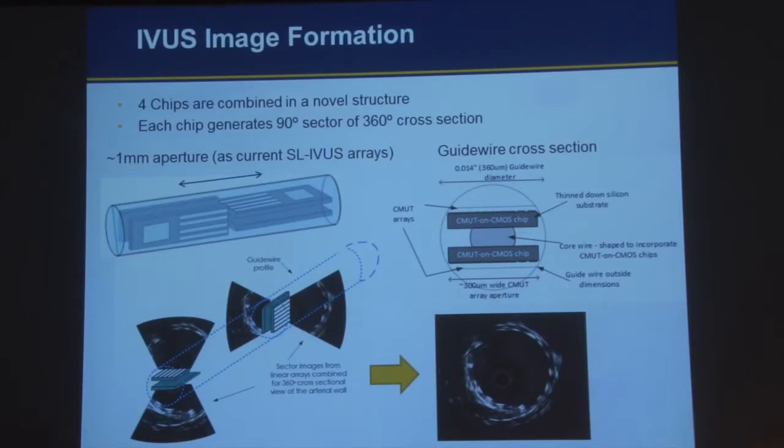And the thing is, how you put it together is exactly the same way the pressure sensor is put together. They have a chip, which we just have basically 2 chips, and they're all thinned down to 50 microns and glued and all that, so it's all taken care of. They can actually put 5 cables already, combining pressure sensor and a flow sensor on a guide wire. So those things are already there for us to use.